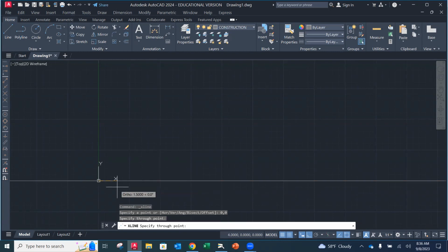I'm going to click. And it's in place. Now, if you just move your cursor anywhere else, notice that behind where you just clicked, you now have that gray line. That's your construction line in place. That's an entity on the screen itself. Now, you're still in the command. You can go vertical through that 0, 0, and I'm going to do that. And then you can just click anywhere. And now I've created both a horizontal and a vertical line in that one command.